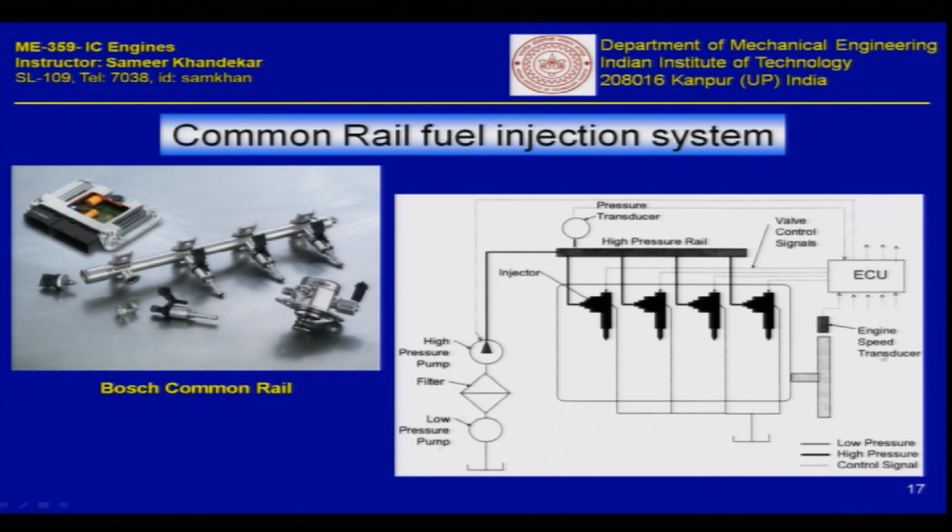Okay. So, you have control signals through which the ECU determines how much fuel is needed at what particular timing, and since they are all solenoid operated, it is very easy to control the timing. The lift and the closure of the pump is easily controllable by relays which get signal from the engine control unit. So, again the system is similar.